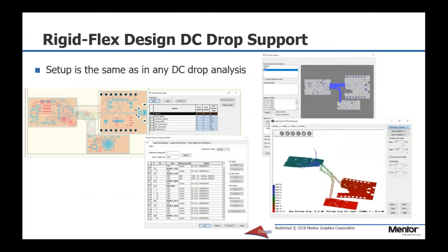An extension of the multi-board support in HyperLynx VX.2.4 also supports DC drop analysis for rigid flex design. Again, the setup is the same as for any DC drop analysis. You can see in this example the results of the rigid flex simulation.